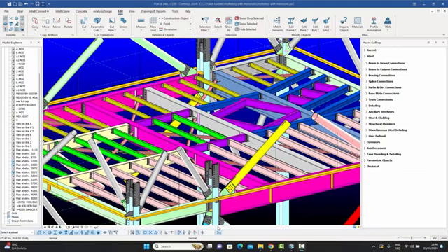And I've shown you how you can basically create as many user-defined attributes as you want. And now, obviously, once we've created them and defined them and assigned them to the different objects, which, like I said, you can assign them to your profiles, to your plates, to your generic solids, to your bolts, or basically any object type which you have, you can assign them.